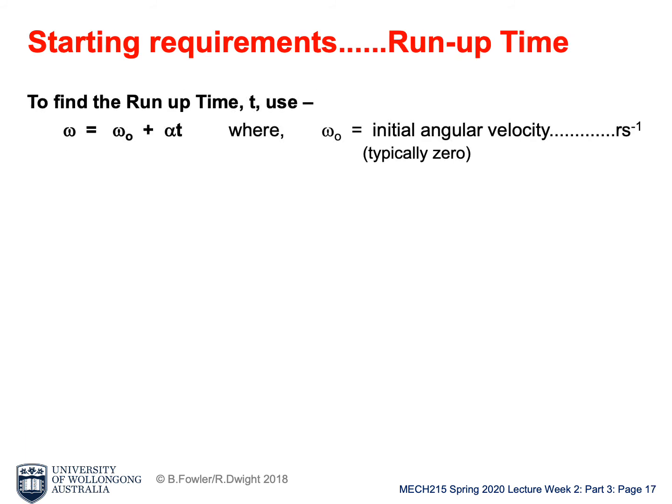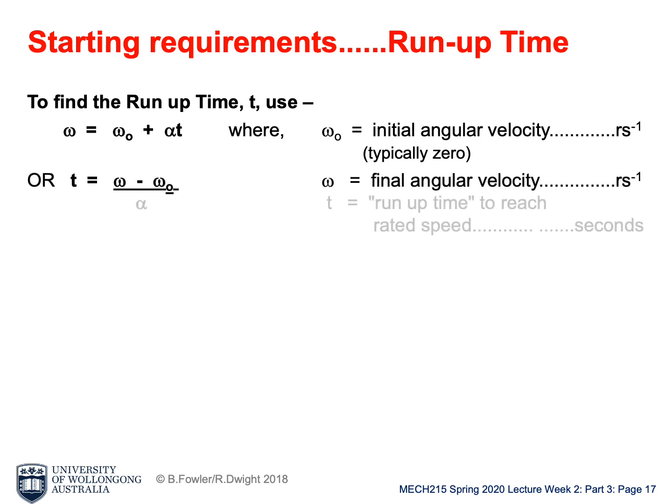Now with the T and J, we can actually calculate acceleration alpha here. For the acceleration time, we normally start from omega 0 equal to 0 and get to omega, which is the RPM of the normal running. And we change its form. It can also be shown as T equals omega over alpha.